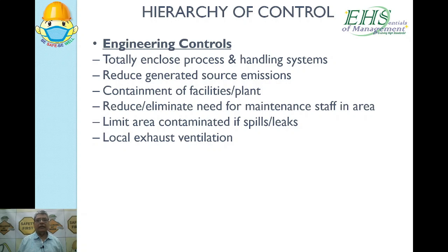So there is a containment of facilities or the plant. So you create a boundary or the area. So you create the bunds for the tanks, where the different solvents are stored, or the oils are stored, or some inflammables are stored. So even if there is a spillage, they do not spread to a larger area.